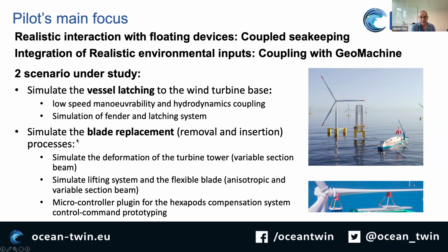And the second tricky part is the blade replacement, where you are high up in the air, everything is flexing, everything is moving, and you have to insert the blade inside the rotor within the precision of less than 1 centimeter. And you have those two tripods there that will try to maintain the relative position of the blade with the rotor based on some sensors.